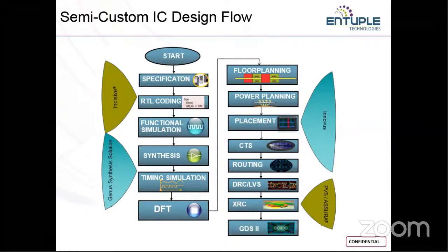We compile the design to check the syntax and semantics, and then we elaborate it to map the logic that we mentioned in our HDL along with the tool. For that, we need some library mapping. That is what we do with the functional simulation.